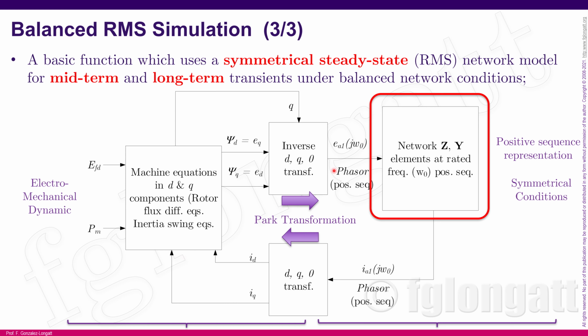And that is where the DQ0 transformation, the Park transformation, starts to be important, okay? That is inside PowerFactory, but PowerFactory includes this kind of transformation internally to do the job for you, okay? But in this case, again, we have dynamics represented by differential equations here, for instance, the machines, and we have algebraic equations covering two sets. Differential equations coming from the transformation and algebraic equations coming from the network, okay?